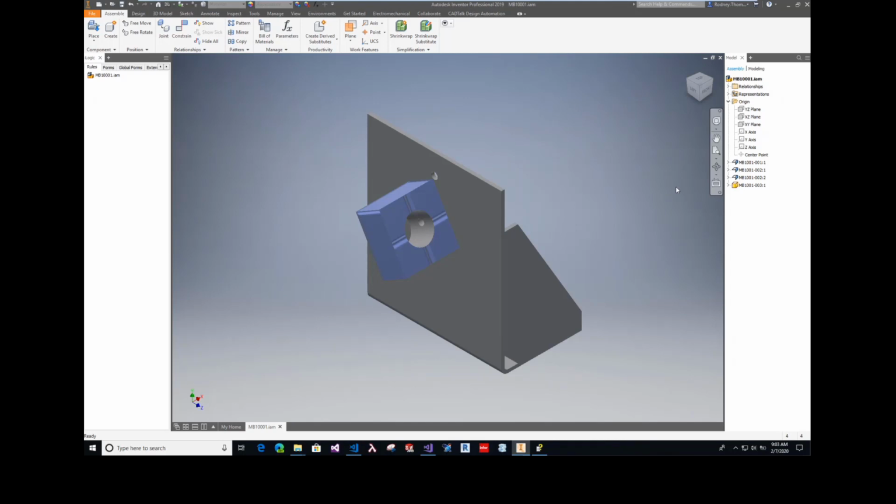It's just the physical size of it that changes, which means you need a new model for each different size that you have. And the typical workflow for an engineer to do that would be to find this model either inside the vault or whatever system they store it in, run a utility which will copy each of the files and rename them, and then save them somewhere. So they've made a physical copy of each file. They either do that or they open up each file one by one, do a save copy as, and then reassemble the assembly back together again of the new changed pieces.